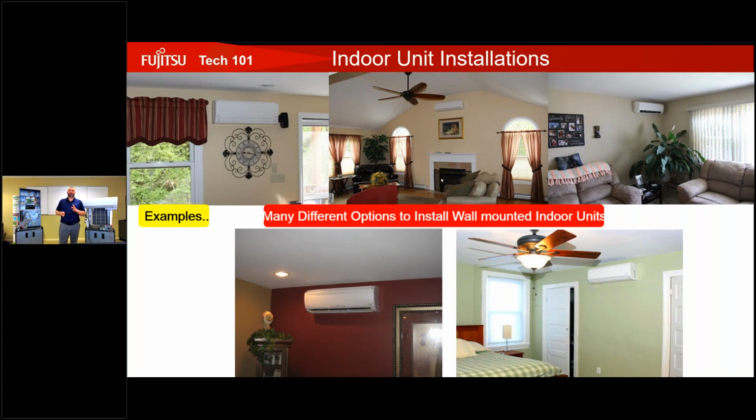But that's really a good installation, because when we're putting these pieces of equipment on the wall, one of the things we want to do is cover the point of heat loss. All right, the biggest point of heat loss in that room is going to be located at that big window. So 10 to 12 inches off of that front wall there, and stay right in front of that window like that. That's really, really good installation.